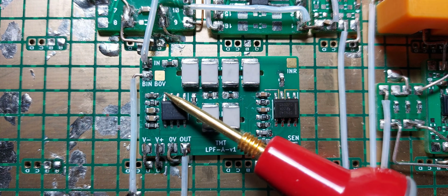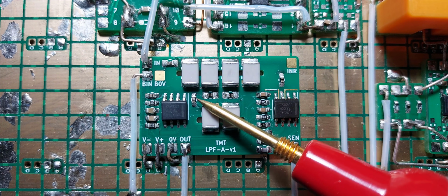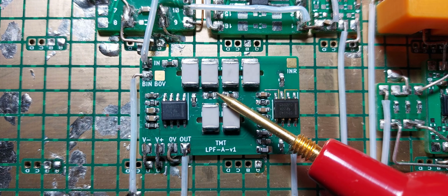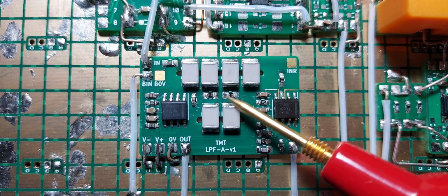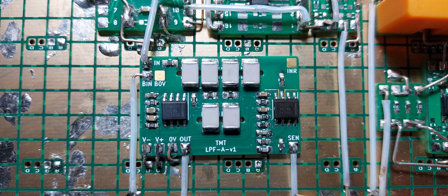For example, the 1 kΩ resistors on the inputs of each op-amp prevent the input capacitances from causing current spikes. The feedback resistor on the op-amp is split and an additional capacitor added, which adds an extra order to the filter for faster roll-off. The addition of a sense input is also a nice touch.